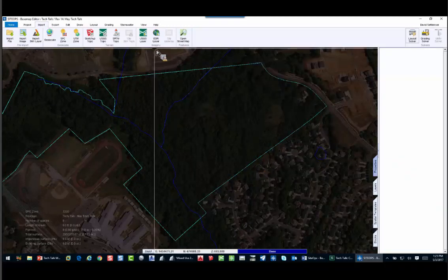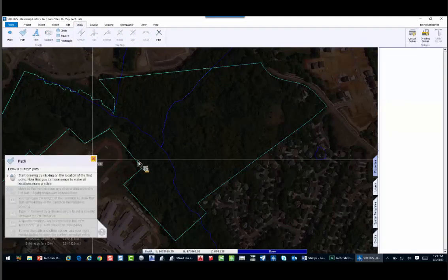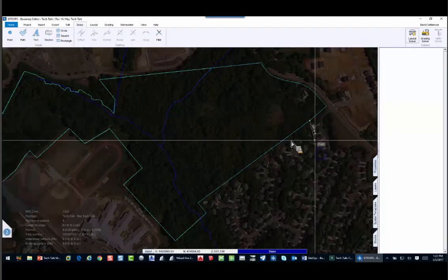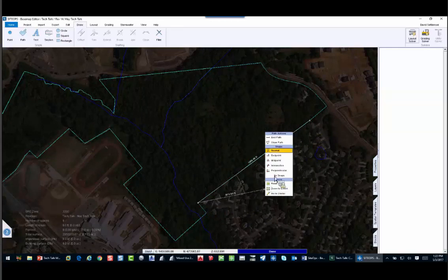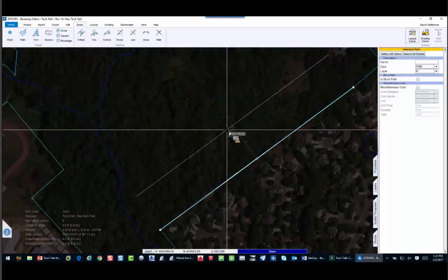We're going to start setting up a street center line. So let's go up to draw, and I'm just going to do a path to start with. I'm going to do a nice easy way. Let's turn off the help. I'm going to just draw a path, say along this edge right there. And I want to offset that path that I just drew. So let's see, the lot for an R4 is 133.5 deep. That's the requirement.